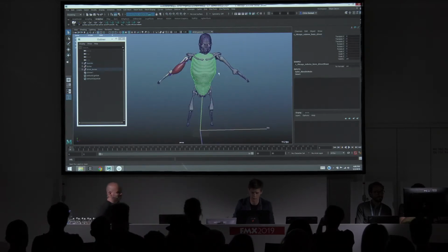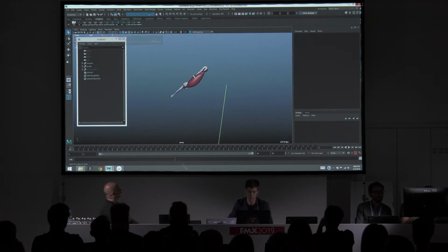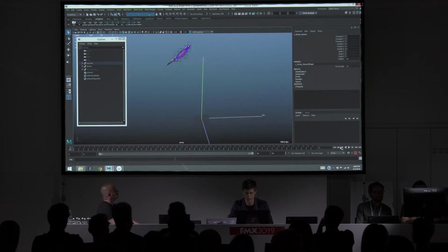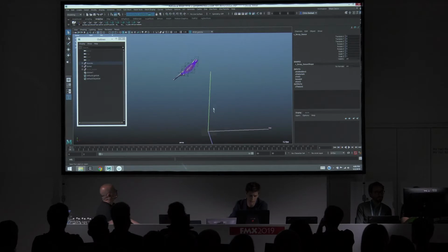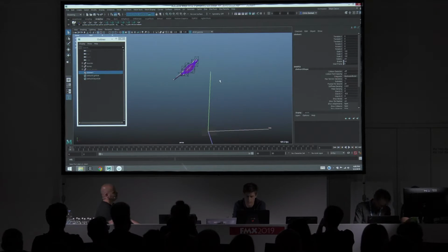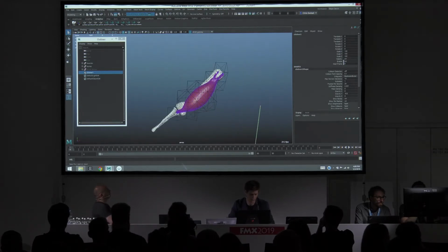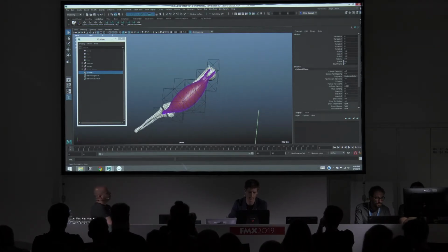I'm just going to hide a couple of these other objects so we can focus on this area. If I play this back now, you're going to see this object drop in space like that. So you can see we got some new stuff in the scene. This solver node here is akin to the nucleus node in nCloth. It describes some general things about the system. And we also got this tetrahedral lattice here. This is key to the core of what we're doing at Ziva with tissue.